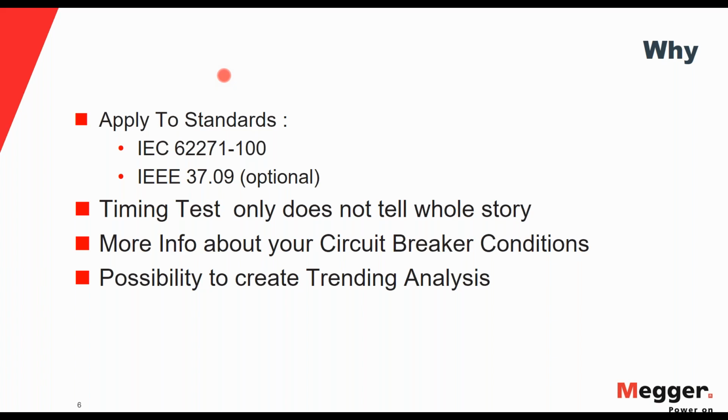You get more information, as I showed you with the parameters in the previous slides, and you can also create a trend for your circuit breaker mechanism, as it's the biggest part that really fails mostly in circuit breakers. So to give you even more insight into why it is important to do a motion or travel motion test, I have two case studies showing the benefit of doing a motion test.